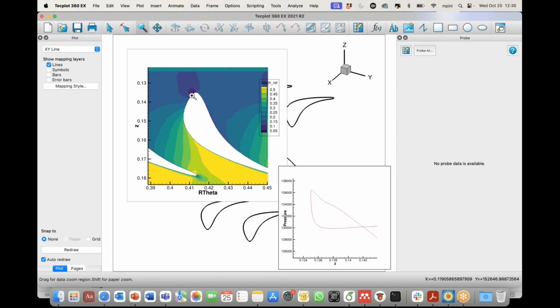I was curious, isn't this what has an impact on the stage-to-stage efficiency? Yeah, very much. Well, what happens is that, pretty sure that after this stator, in real life, you would have another rotor. Otherwise, it wouldn't make sense to have a stator like this with such a high outlet flow velocity. So this is not just an outlet guide vane, it's really a stator.